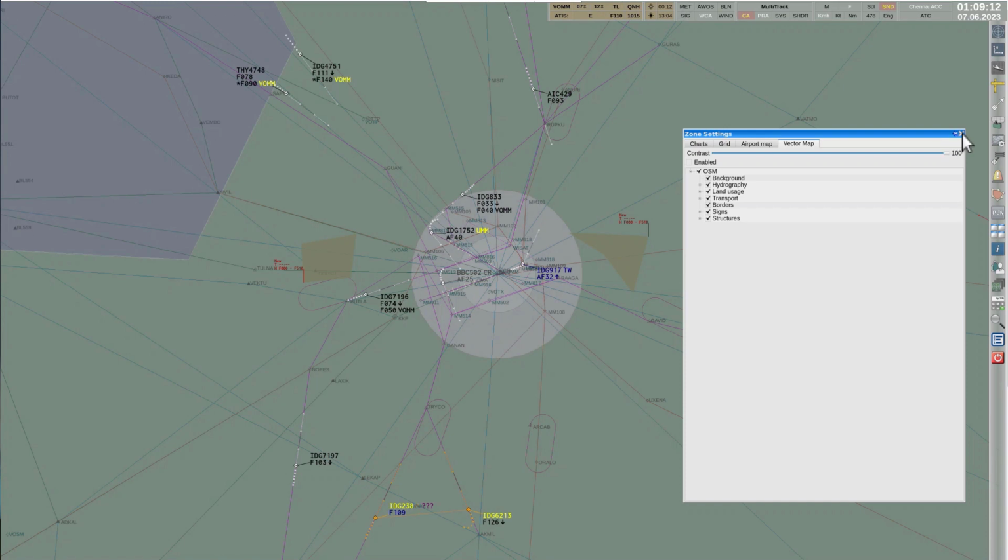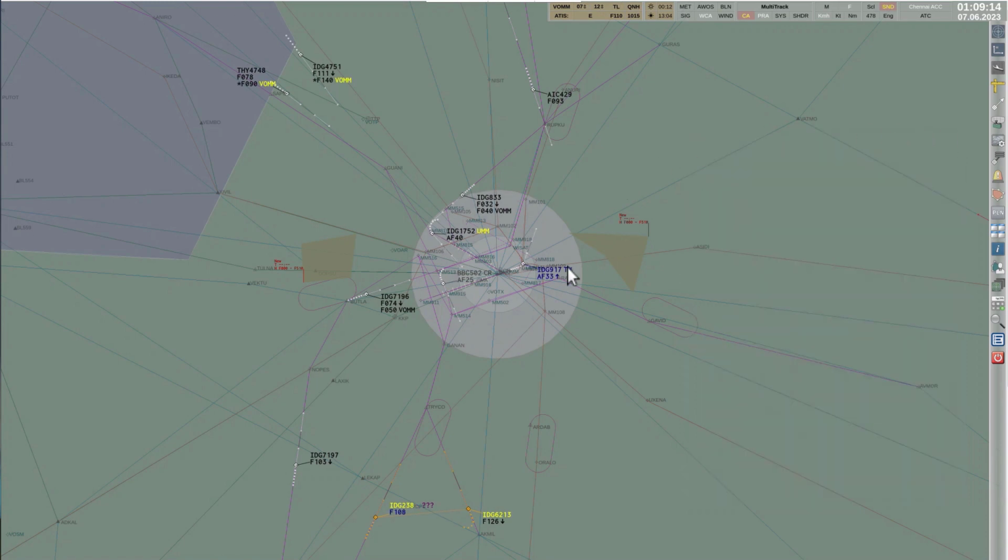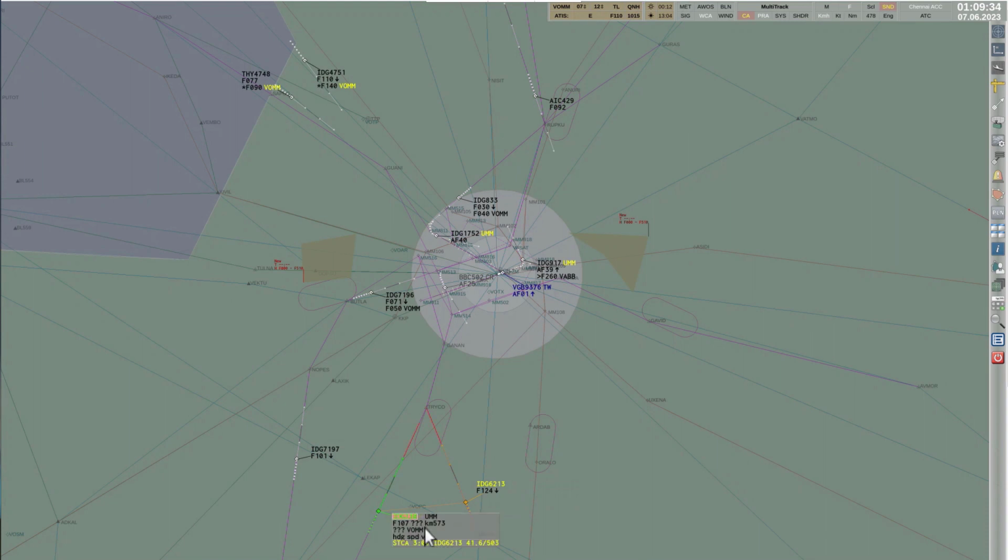For the track position displaying, the Alpha system performs receiving, processing and fusing of data from almost all kinds of radar sources, including primary, secondary surveillance radar and Mode S radar. The system also provides ADS-B, MLAT and space-based ADS-B data processing. This data is used for 4D trajectory calculation and for the most precise aircraft positioning display.